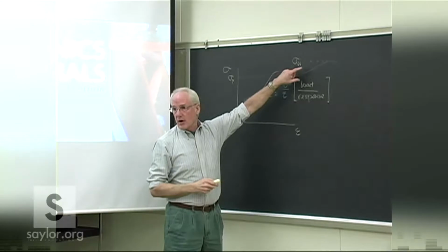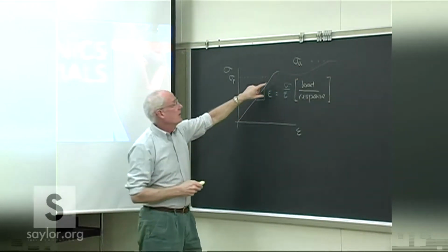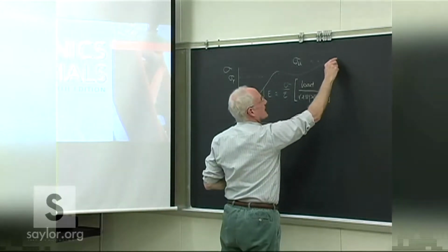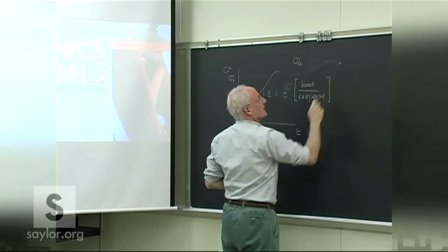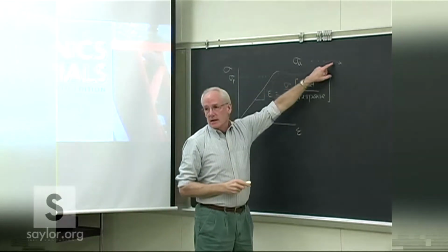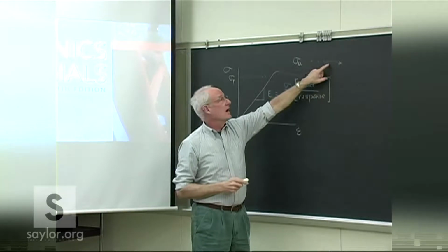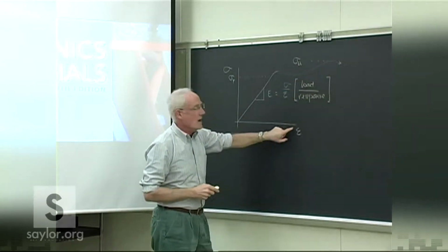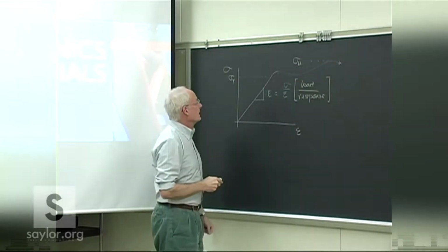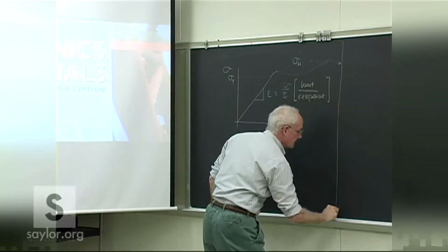For the most part, that's not a design region you want to go anywhere near, because once you're past that, then the necking starts, and sooner or later there's rupture of the material. Certainly, there's substantial plastic deformation if you've gone into that region, because now you're way out here in the strain. An awful lot of deformation has occurred by then.